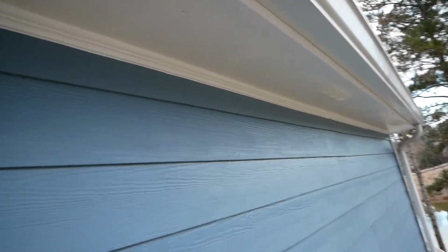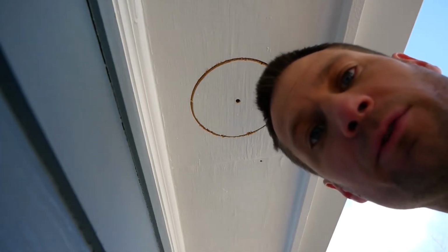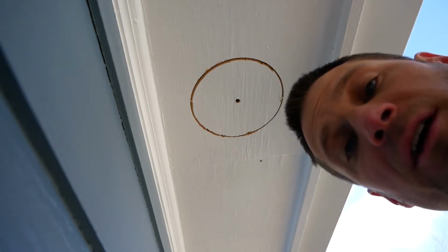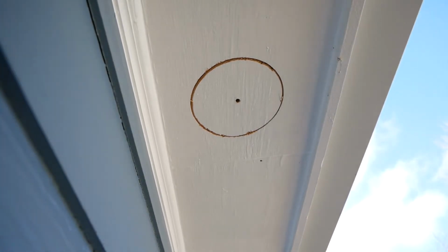Now, I've already drilled a couple holes here, as you can see, and the midpoint right there is right on the joist, so that's not going to work. So I just off-centered it a bit, and that's the place where we'll drill the hole to put the dampered vent. So let's go ahead and get that drilled out and get the duct installed, and we should be able to take care of this. Okay, so I just marked out a hole for that soffit vent. And I don't have a hole saw that's large enough to cut that out, so I'm just going to use a jigsaw here.